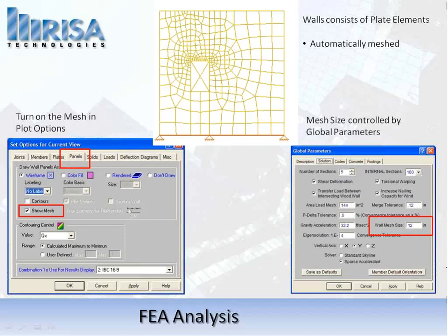So if I drop in some joints in here for loading, or if I have a line constraint, maybe I have a diaphragm cutting across somewhere. Not typical that you'll run a wall up over a diaphragm, but maybe you're doing some balloon framing and you actually have a diaphragm tying in somewhere along that height of that wall. That will actually mesh to it. Okay, so it's a real good tool that all of these things are meshing automatically behind the scenes for you.